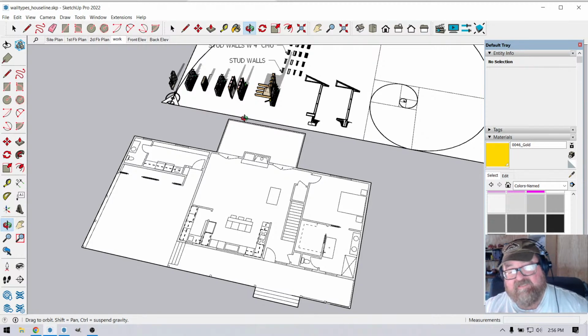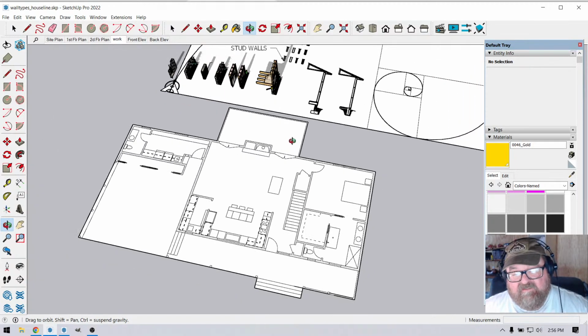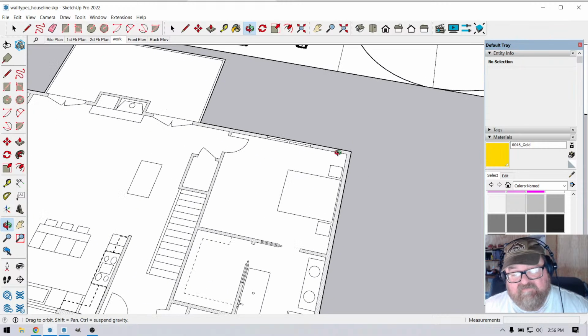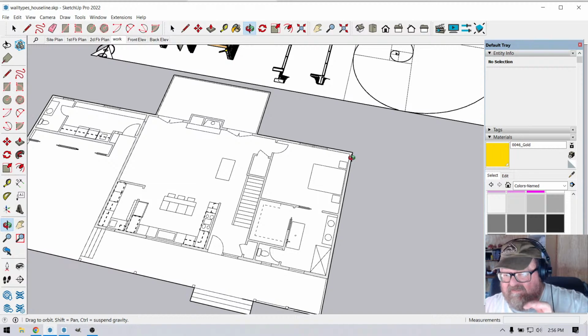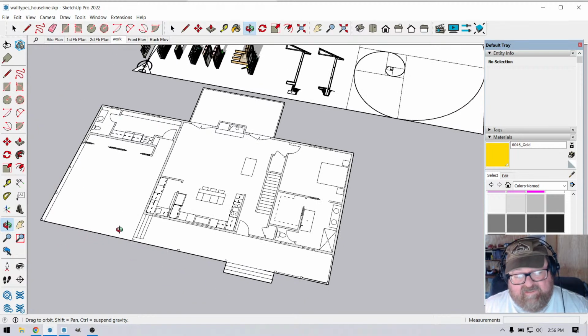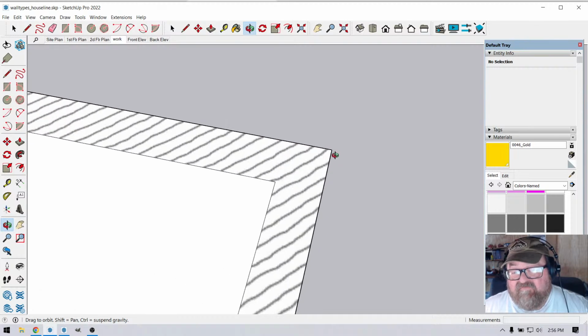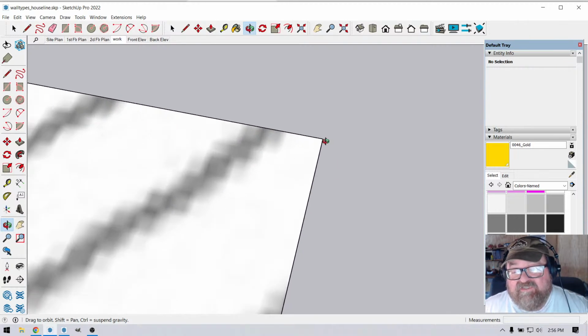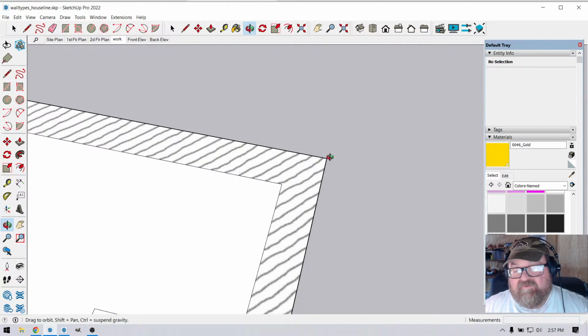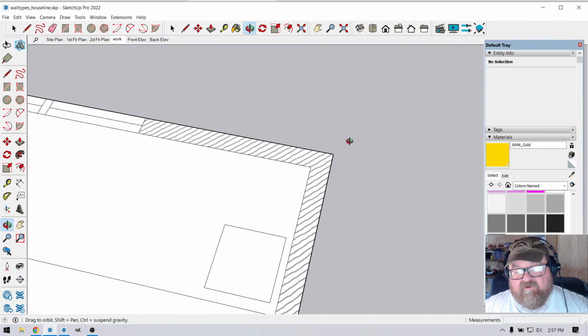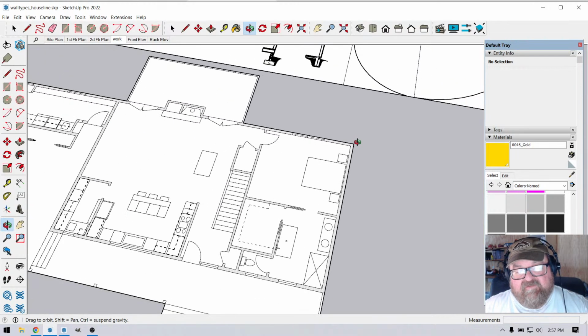I have a guy, his name is Ski. We call him Ski, it's a nickname. He comes out, first he will stake out the corners of the house based on the house line, and then we will dig the footings, we will pour the footings, then he will come back and place pins, little nails, at the very corner of the house line, okay? And that is a legal point in the ground that you can legally say, my house is at the right point in the property, okay?